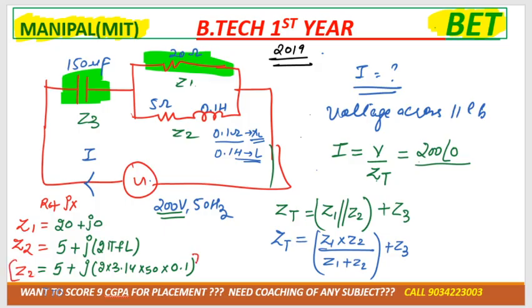So after solving, can you get the value for Z2? Now similarly, you need to get the value for Z3. What is Z3? In this, no resistance is there. So can we write it down as 0 minus JXC? Because R minus JXC, R is not there, so 0. XC again we need to calculate. And what is the formula for XC? 1 by 2 pi FC.